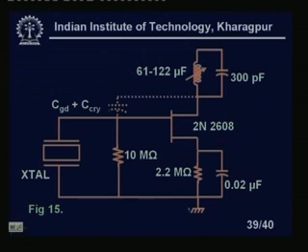So, this oscillation frequency does not depend on these resistances, capacitances and all these things. It will depend totally on the crystal, and the crystal parameters do not change, right. So, obviously, I can get a very stable signal from the circuit.